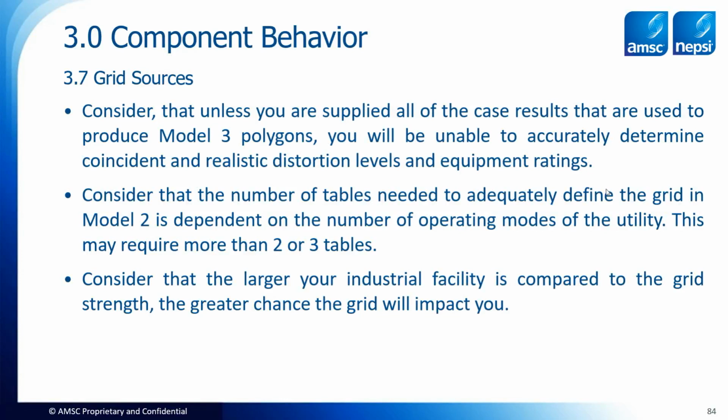I personally like model 2 the best, but you also have to consider how many of these tables you need to adequately define the grid, because that's going to depend on the number of operating modes and what we consider to be normal operation and contingency operation. So you may require more than 2 or 3 tables to simulate the different grid operating conditions and how that resonant characteristic of the grid will change.